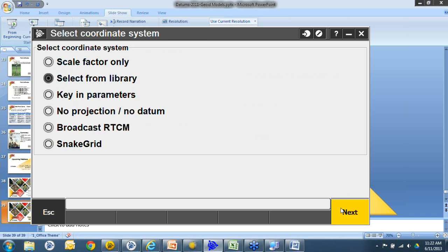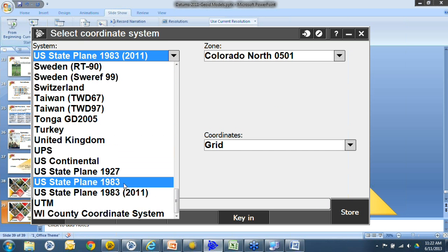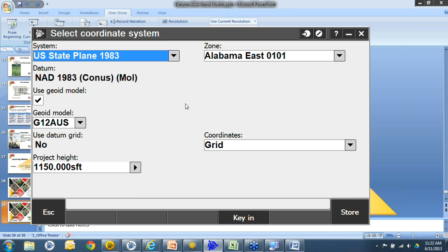I want to just make sure everybody walks away understanding, we're not here to explain what NGS is doing per se. We're trying to show you what our software means by using NAD83 CONUS. What we were trying to say is that this NAD83 CONUS selection is a 0, 0, 0, which means no transformation. We're not referring to a NAD83 and an epoch date like HARN. No, because Trimble doesn't designate that in their software.